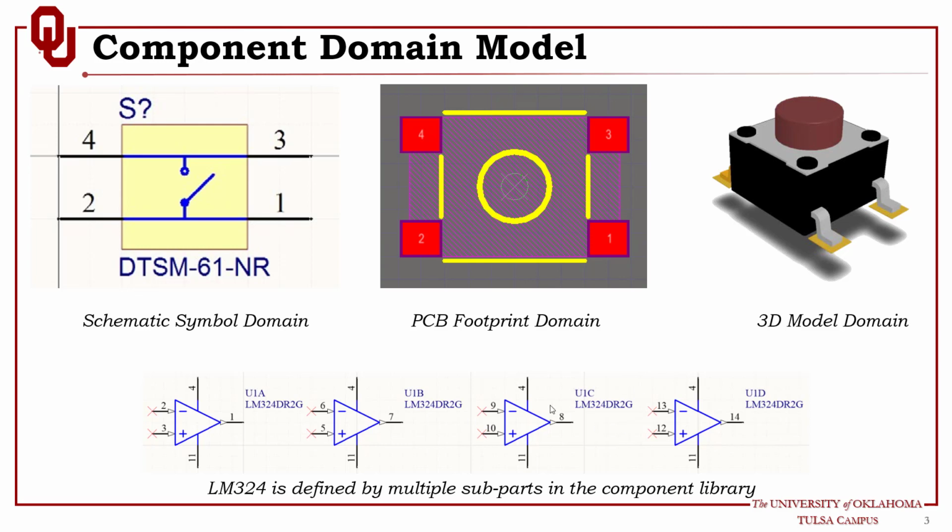Also, we will see how we can create a component with multiple modes, like if you have a resistor in US style or in Europe style. So how we can create a component that includes both styles, and you can select which style to go with during the placement.